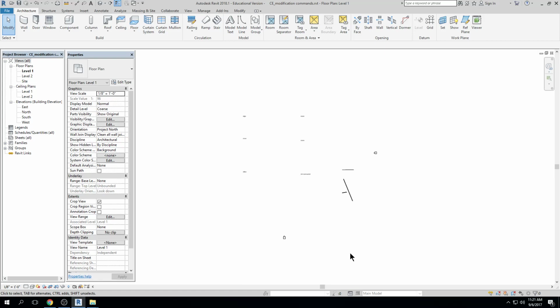But one thing I want to point out that's actually pretty obvious in this illustration is that all of my items on the screen, when I changed the scale, scaled with that scale, right? So unlike AutoCAD, where unless you're using annotative blocks and different things, it's generally kind of dumb annotation, where if you change the scale of your drawing, you have to change your dimension style and your text style and all of those things so that they're the right height according to the scale you have drawn everything in AutoCAD in. What's really great about Revit is that process is automated. So if I change the scale, the text size automatically changes and all of my annotation changes. And that will include dimensions and section markers and elevation markers and different things like that, right?